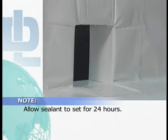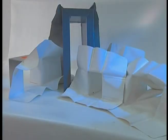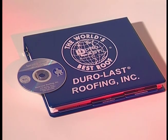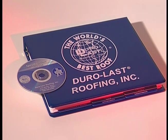Allow the sealant to set 24 hours. This step is not necessary when using Duro-Last vinyl-coated metal scuppers. This completes the outside inaccessible method of scupper flashing installation. For more information, refer to the Duro-Last specification manual.